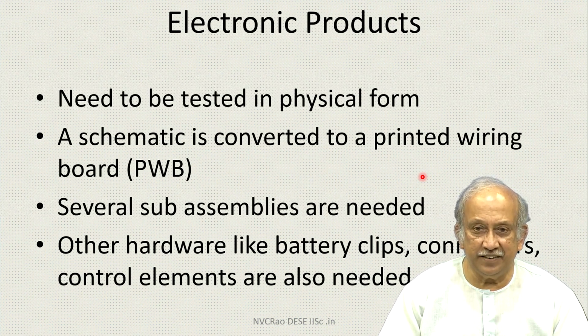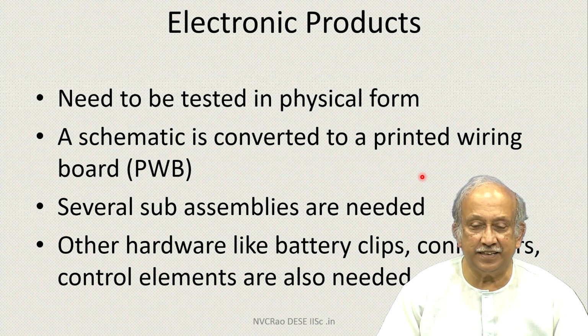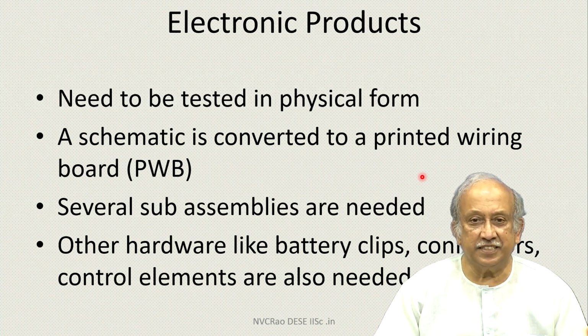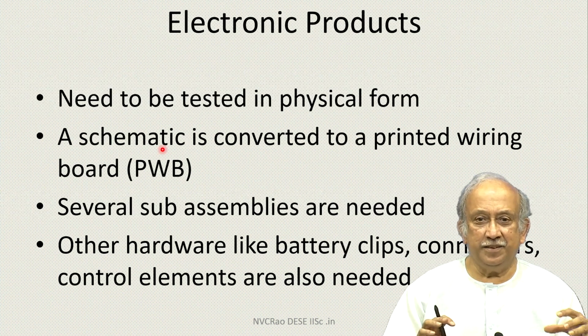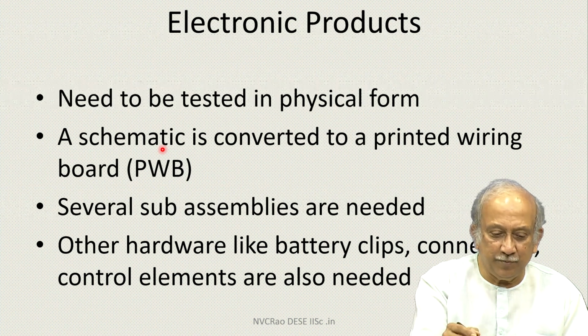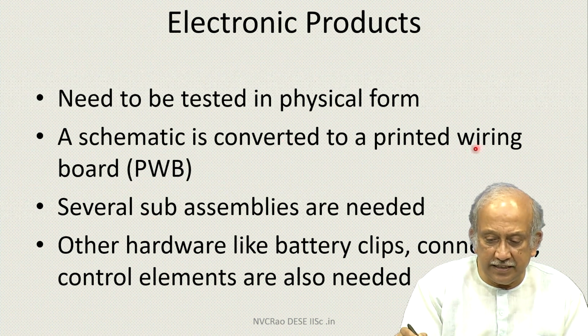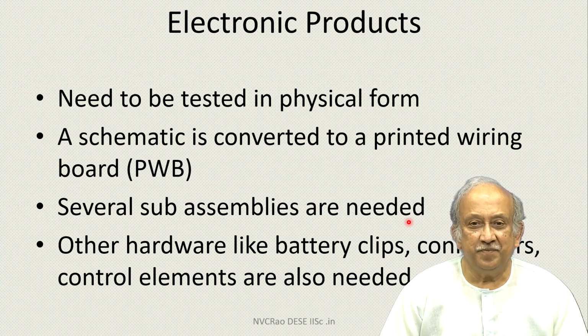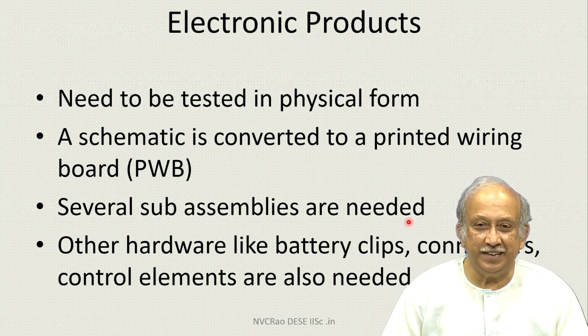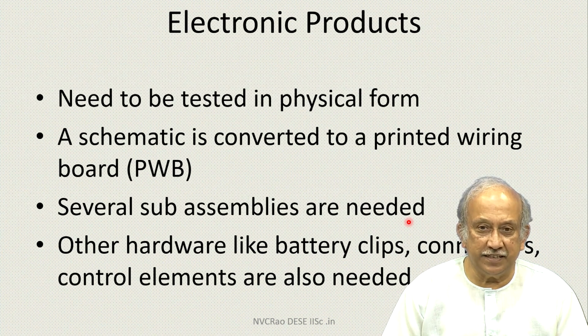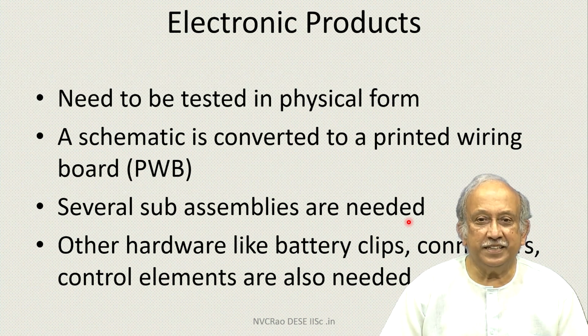And for every device, or directly on the internet, a lot of resources are available on how to connect the schematics together. Now comes the important thing, why we need a prototype. Obviously, the full thing cannot be put onto one PCB. If you put it on one printed wiring board, there are certain advantages, but there are several disadvantages. One is that simple repair is not possible, and it is not easy to put together a simple prototype.